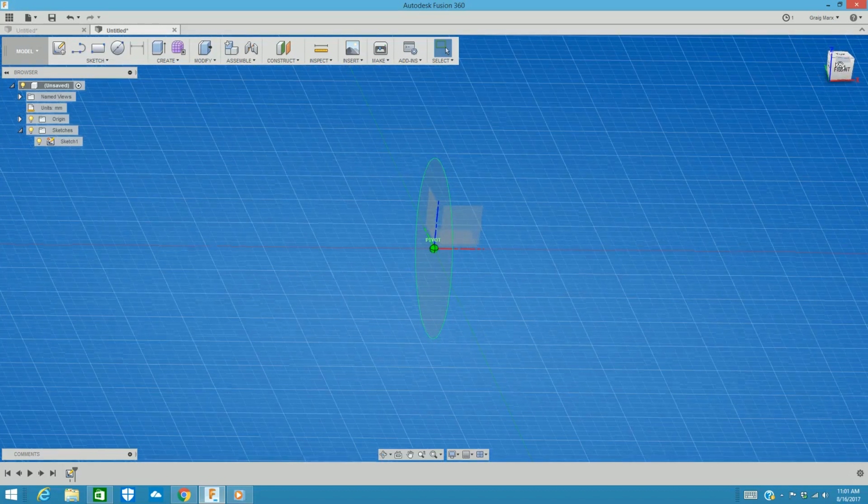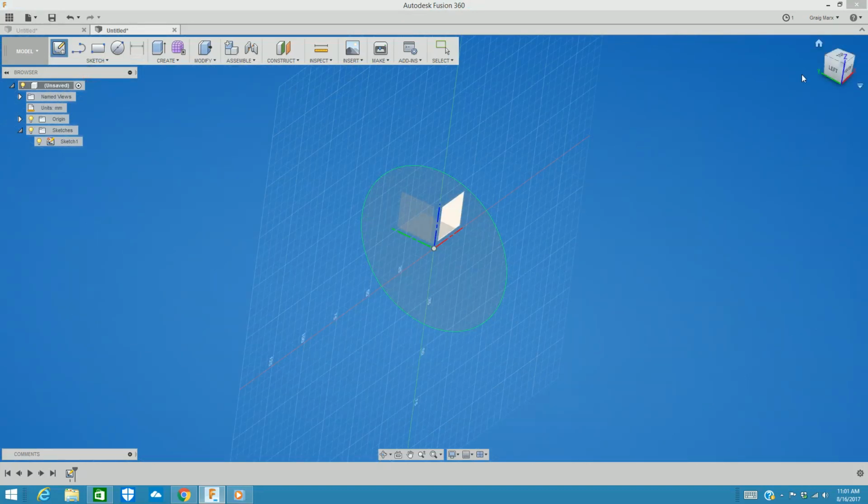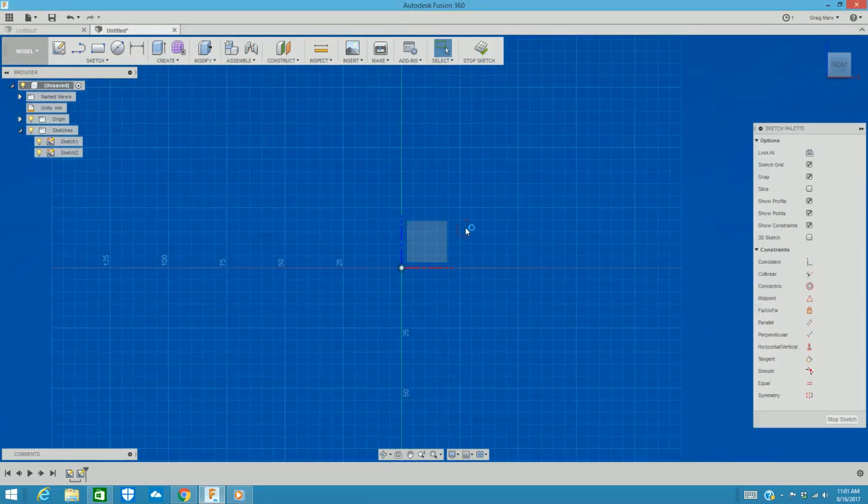All right, let's try some other things with circles. I'm going to go ahead and create a new sketch, pick a new plane, and start over. This time I'm going to create a bunch of circles, and my goal is to show you a couple different ways to do this. If you're ever going to try to make a cylinder, well, a cylinder is kind of different than maybe a pipe. A cylinder can be solid. A pipe would have a hollow middle, and it would just have thick walls. So in that aspect, you might need two circles, one inside of another.